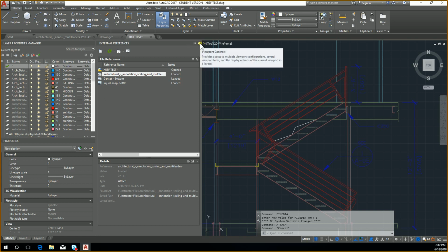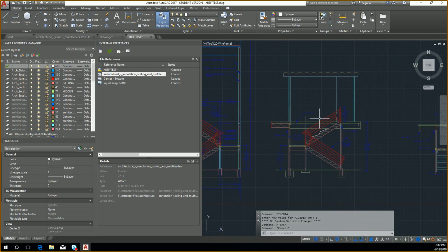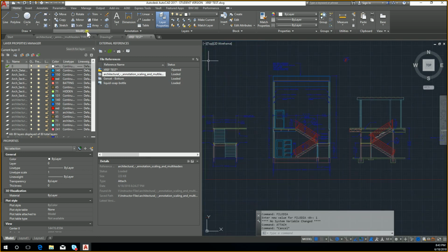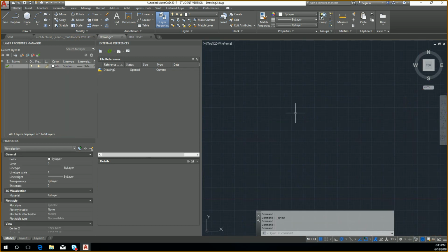So again, this is a very simplistic looking command, but very important that we are all understanding how it works and the ramifications of how it differs. So again, just to reiterate, if you are looking to start off with a block to work with and modify, the insert command is good, because you will bring in your block, you can go ahead and explode it and continue on.